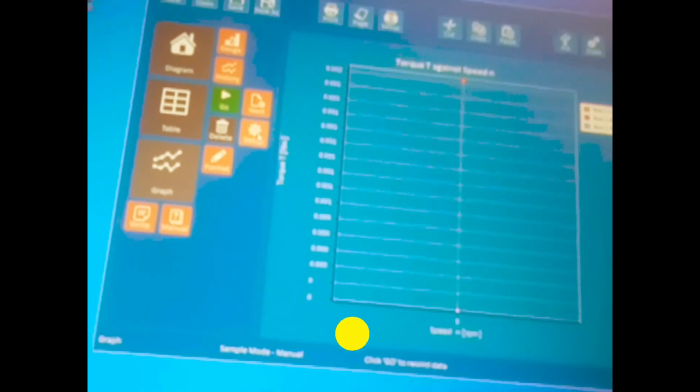We can also set flow rate. We have the speed, and on the y-axis we are getting torque and brake power in watts, and torque in newton meters. Similarly, you can also check efficiency. So it will give you these three properties and the relationship between these properties and speed. Okay, let's come back to this section.